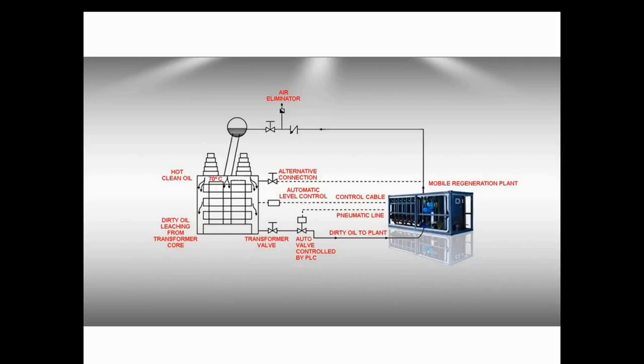In the USA, there is a company called Cooper Power Systems, which produces FR3 oils. These are vegetable-based oils and they are not recommended for mixtures with mineral oil because of probable negative reactions.